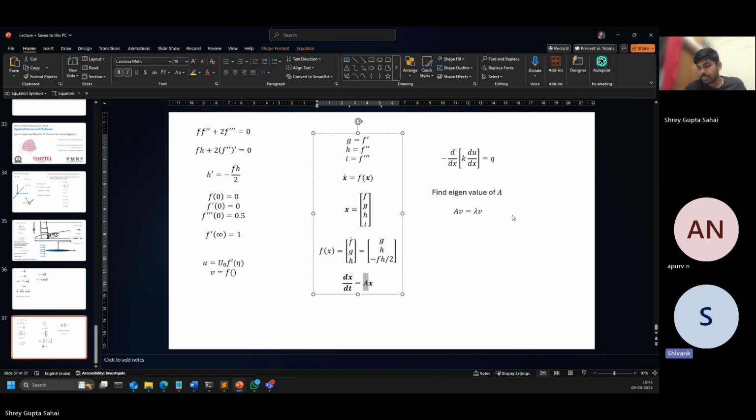Okay, then you can take the strain or stress vector. As I was saying, in stress or strain, you know that there are principal directions, right? There are directions along which the material is just stretched or compressed. In those directions, the material is not changing direction.